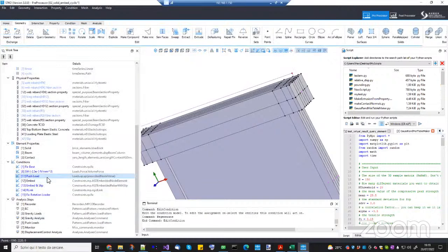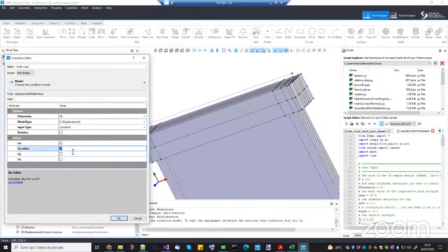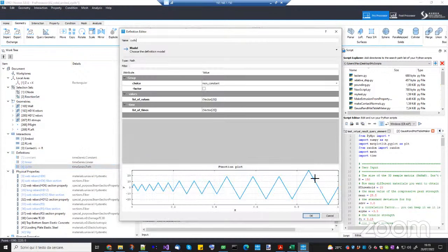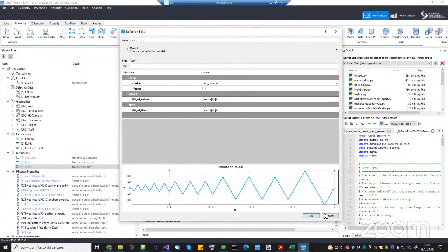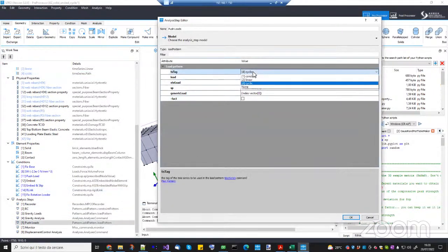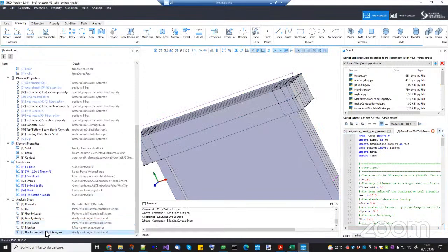Oh, of course, now I change the push load to -1 instead of -30, because now I'm using the cyclic load where the absolute value is already the total displacement, okay? So the other change is simply that the push load now has another time series, which is the cyclic one. Massimo, a question.